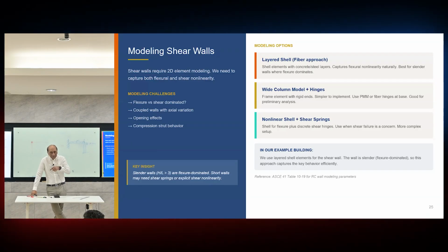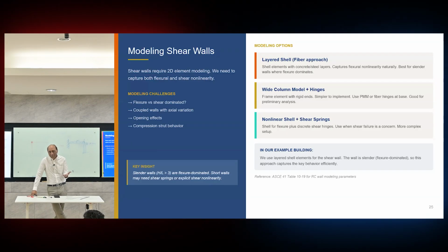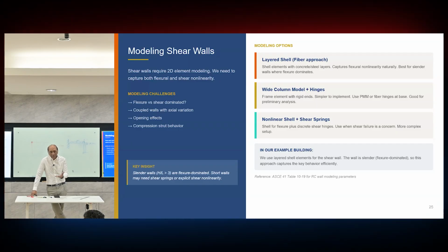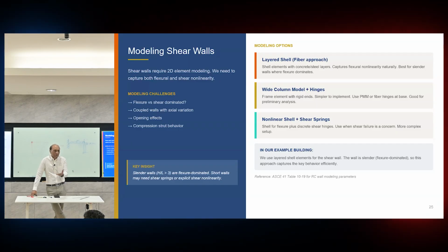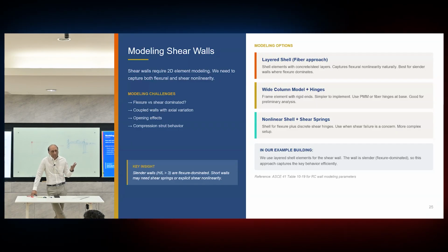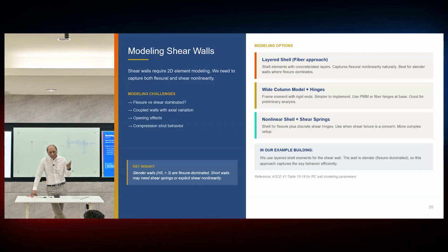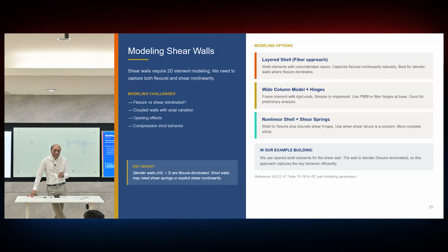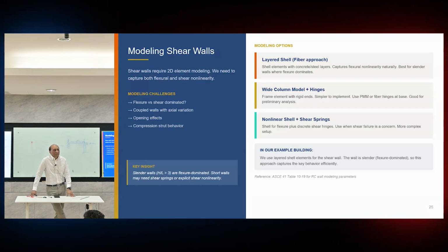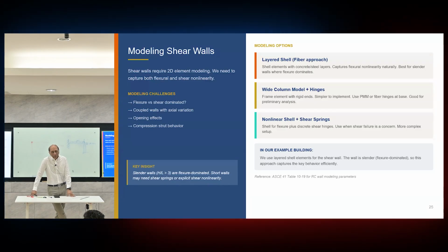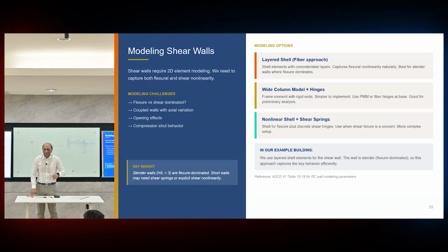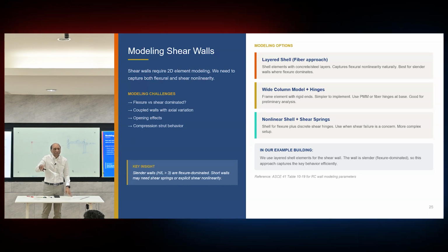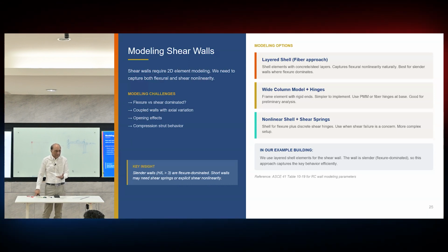So they think about the shear wall as if it is a big column section. As I mentioned to you, CSI also still uses this for shear walls. So in many programs, people who are not familiar with nonlinear layered shell will still use the fiber hinge modeling for the shear wall as well. Define the cross section, and then the program calculates the PMM for that and assigns it over there.